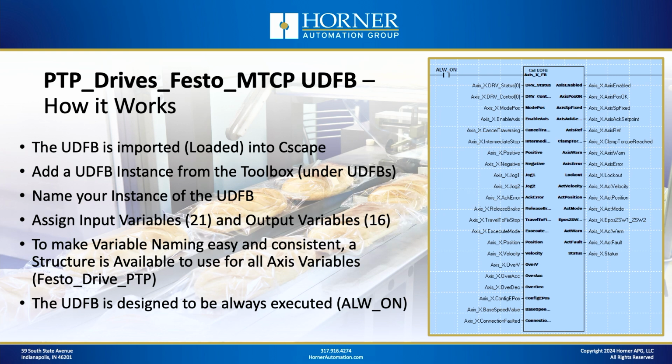Now, I didn't design this from scratch. I basically modeled it after an existing add-on instruction that I believe Festo created for use with Rockwell type PLCs. So this follows the same approach. And again, it's quite substantial. You've got 21 or 22 input variables, I believe, and 16 output variables. And the user-defined function block is designed to be always on.